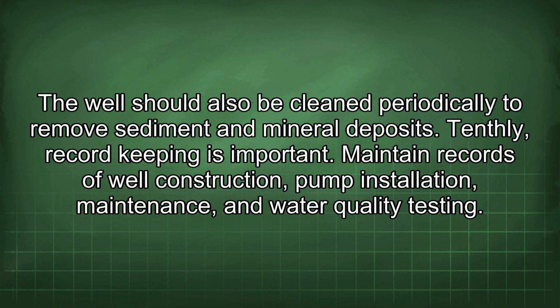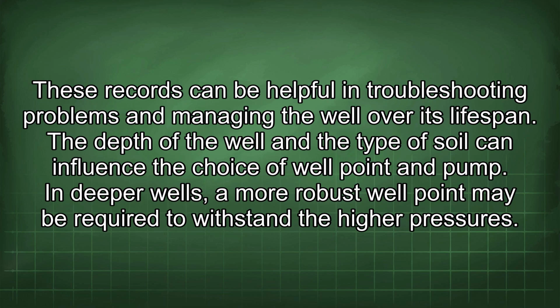Tenthly, record keeping is important. Maintain records of well construction, pump installation, maintenance, and water quality testing. These records can be helpful in troubleshooting problems and managing the well over its lifespan.